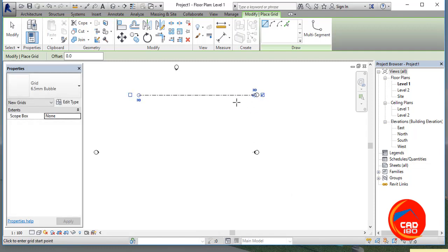From there you can choose multiple grids, and these grids can be at different distances too. So what you will do is give an offset. Type O, and after that pick a point. We can give an offset of 3550. If you give a column or a line which resembles it, that's a line position, and that's why we give the offset value. So I will give 3550, and now I just click on Pick Lines.